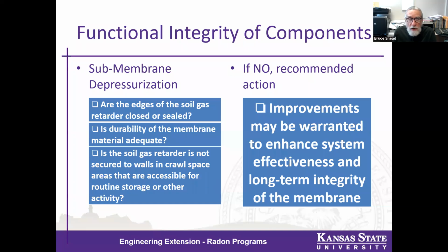Are the edges of the membrane well sealed? And is it of durable material that will withstand movement, surface activity, storage, etc.? And is it secured properly to the surrounding perimeter wall?